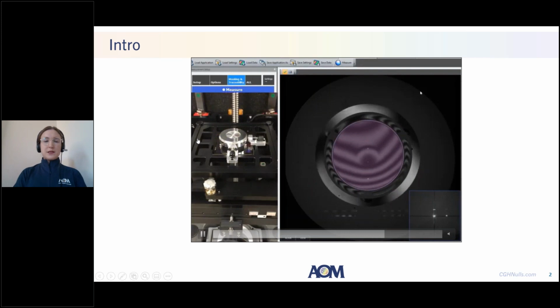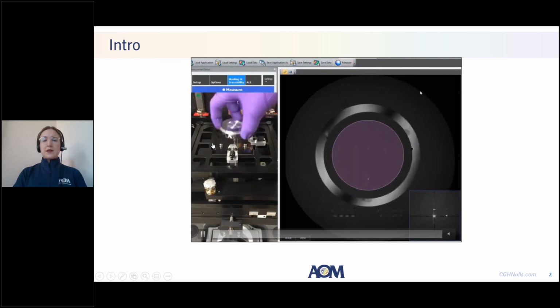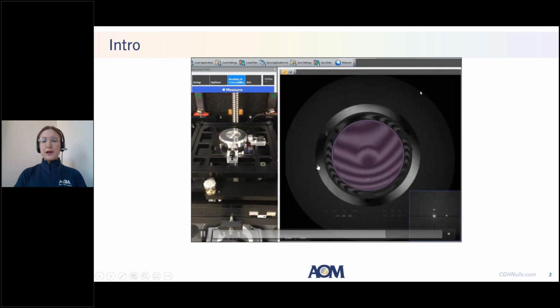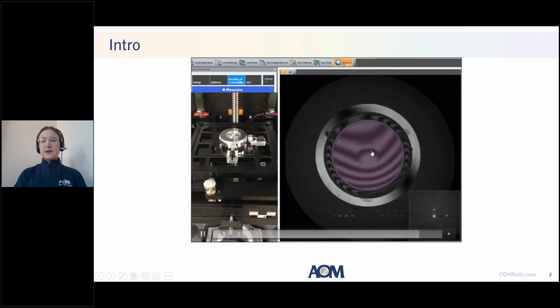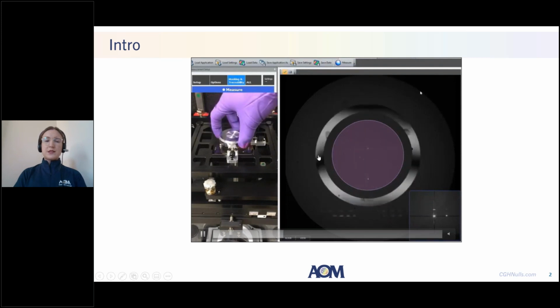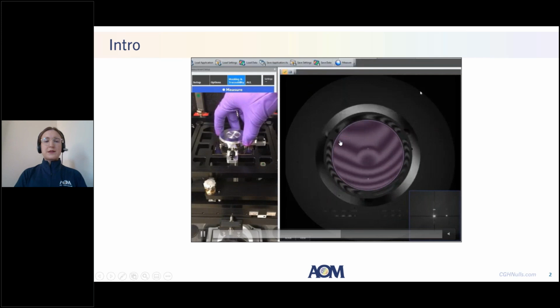And then in addition to these physical mounting features, the CGH includes alignment patterns that provide interferograms. So if you look to the right, we've got these two annular interferograms in addition to measuring the optical surface in the middle there. And these help us understand the alignment of the CGH to our interferometer and the alignment of our test optic to our CGH.